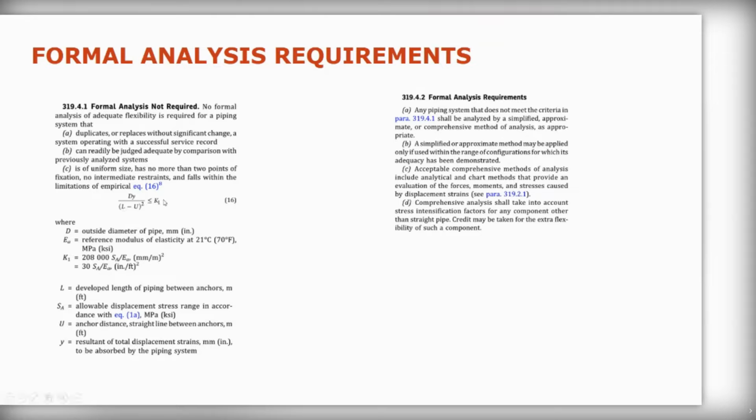Now, with this equation, I'm not going to go in any depth on where it comes from. It's easy to apply if you want to. It's easy to do a check, and you can use it. It's been around for a long time. It's trusted. It's very conservative. So again, sometimes you may be better off doing pipe stress analysis and not ending up with an overly conservative design. But it's a bit of black magic in terms of how exactly they worked it out, and it's based on some nomograms and so on.